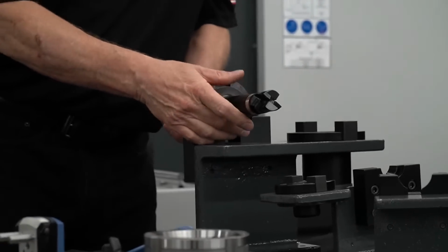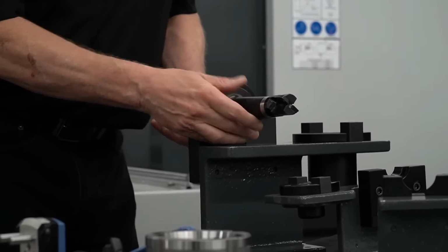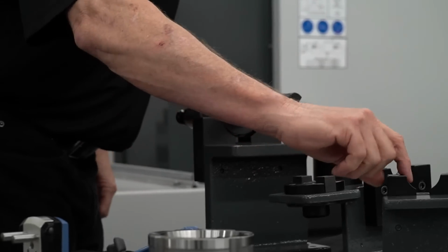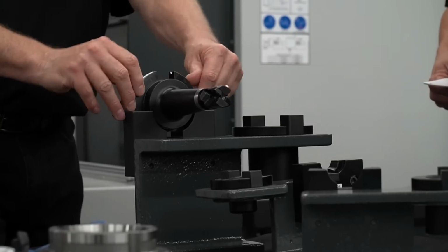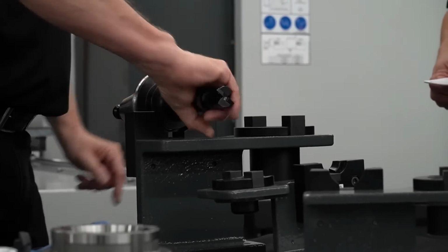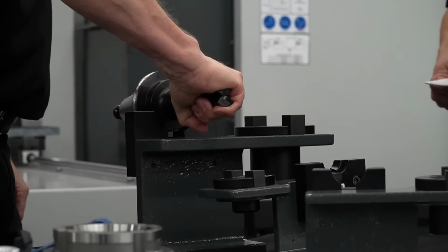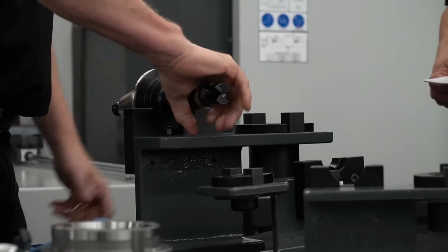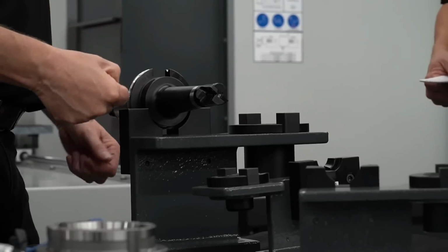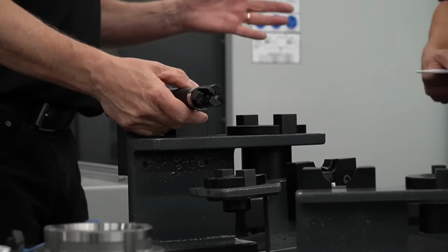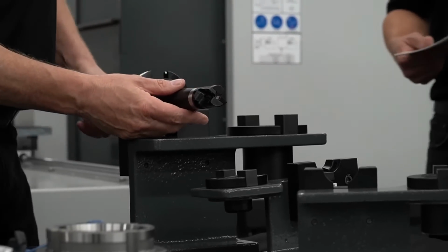How does this work? Well, it's got the actual taper machined in here. And the way this locks into the V-flange on the tool, it's actually locked in there really, really tight. You can lift it in and out very easily, but when you're trying to turn to loosen, even pulling up on this thing, it doesn't pull out of here. It was kind of magic. Much to our surprise. Yeah, absolutely.